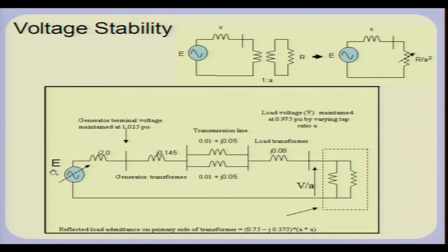Thereafter, this voltage can no longer be regulated because the field current has reached its limit. So, you can't change the field voltage, and therefore the open circuit voltage of the generator, the internal voltage, cannot be changed. In that case, the series reactance of the generator will start in some ways asserting itself, in the sense that the voltage here is no longer regulated, and effectively the source impedance is going to increase very significantly. So, you can have under certain circumstances the source impedance being very large.